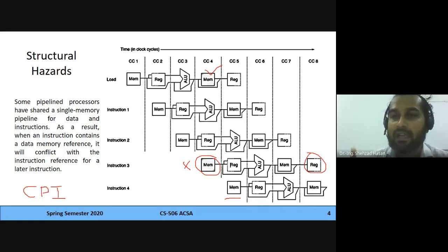So here in our example, an instruction is going to take just 5 cycles. But had we divided our instruction cycle into 8 stages, we would have needed 8 cycles to complete the same task. Those cycles would have been smaller than these cycles, but they would still be considered in terms of cycles. I hope that answers your question. So in this example, we are going to talk about just 5 cycles. If you are asking how many cycles we are going to talk about, it depends on the program. It's going to take many thousands or millions of cycles, so we cannot show all of these cycles. So it's just an example over here.